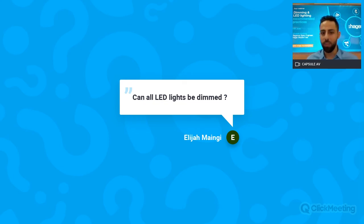No, they cannot all be dimmed. They need to be dimmable. This is number one. And as we mentioned in the quality or in the dimming on the performance, we need to make sure that if it is retrofit, the lamp, you can read it on the packaging, dimmable or non-dimmable, or the driver is dimmable or non-dimmable. So not all LED lights can be dimmed.